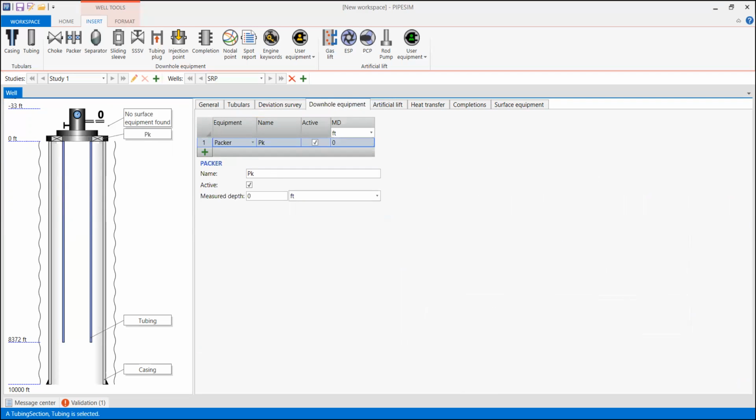We will have a packer here in this example, oddly enough, because usually we don't equip our well, which will have a sucker rod pump, with a packer, because it will disturb the separation between the liquid and the gas. Because we will have multi-phase here coming from the reservoir or from the perforation, and the gas will be separated and go upward through the annulus.